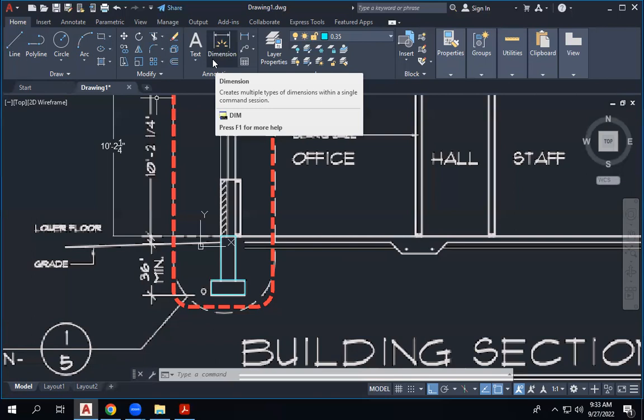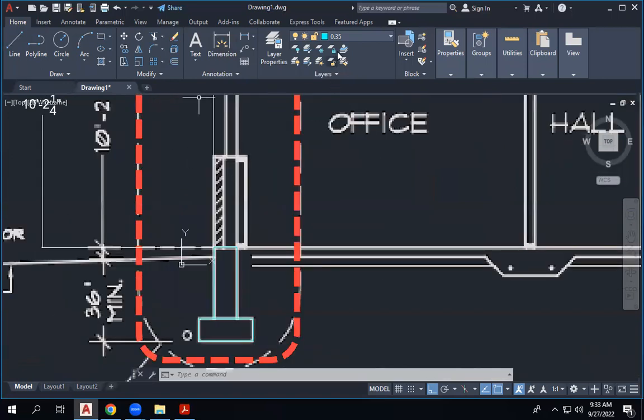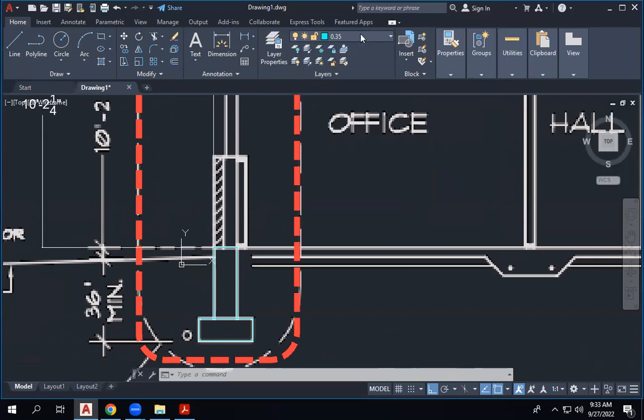You can check it when you draw a few lines, and you can make a PDF or print preview. Just check how it looks. Then you can change it at any time. There is no standard saying that you should use 0.35 for the lines in the materials where it cuts. It's totally your decision what to do. But here I just use 4 line thicknesses to give clarity for the drawing.